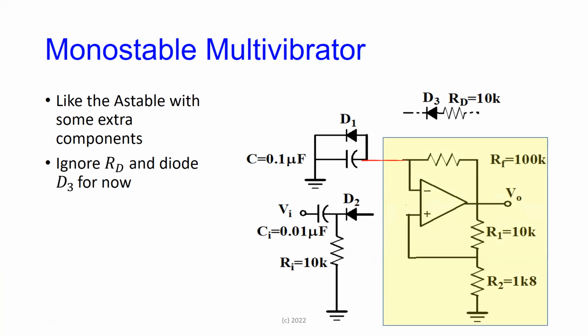So what I'm going to do, I am adding some components here now. I'm taking a diode and connecting a diode across the capacitor. Note that the cathode for the diode is connected to ground. Right, so the same capacitor that I had before, I now basically bypass the capacitor with a diode. The diode is connected to ground.